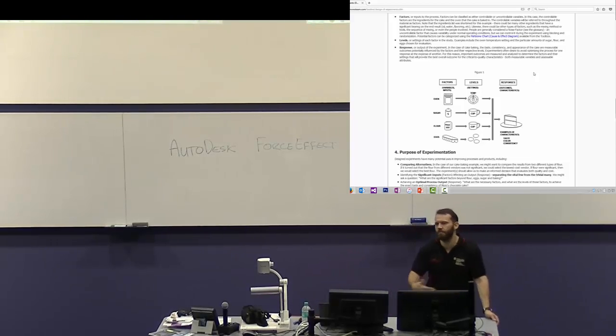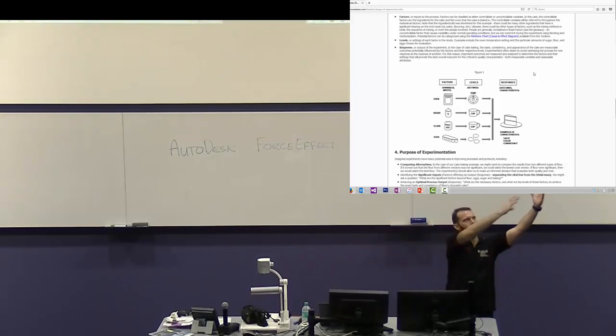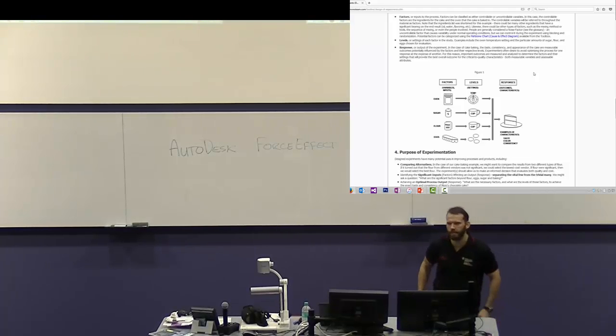Ideally, what you want is to put 17 kilos in the example we had and break it, then get a little bit bigger and break that, and get a little bit bigger and not break that, and that's your threshold. If you have a cross-section this big over here that breaks and a cross-section this big over here that doesn't break, that's not telling you much. You need enough data points to go from breaking to not breaking and have an idea of where in the middle you need to be.